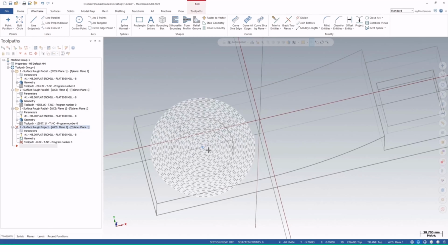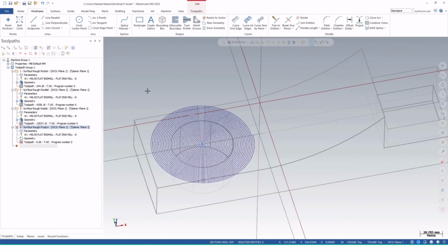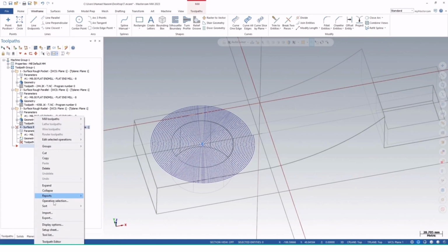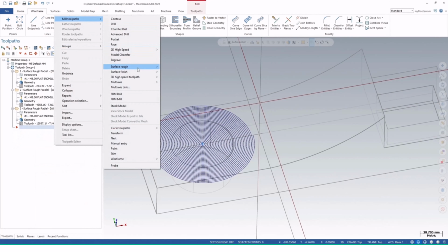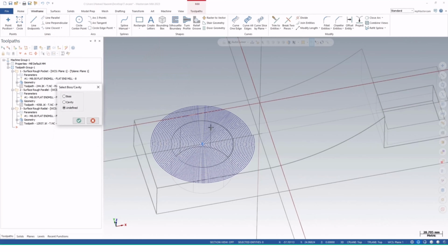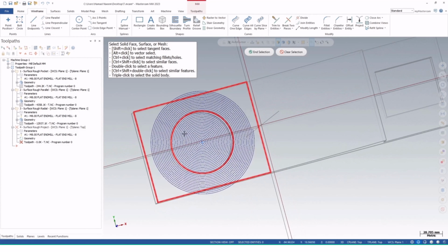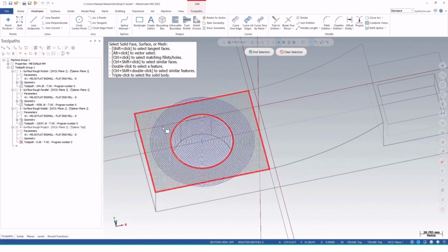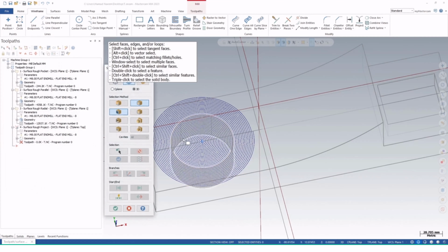work frame. So here what you see is this is 2D geometry, and what I'm going to do is I have projected this tool on this surface. Let me show you. So let me delete this first. Yes, and again go to milling tool path and project. Okay, so I just want to machine that area using those curves. Okay, so this should be my surface area. Okay, and here are my curves. So all these are my curves.